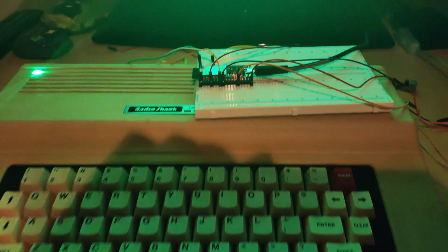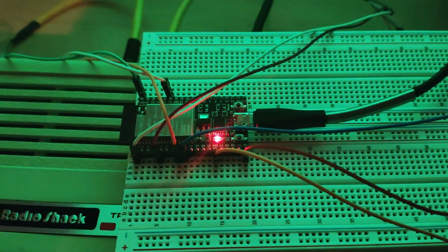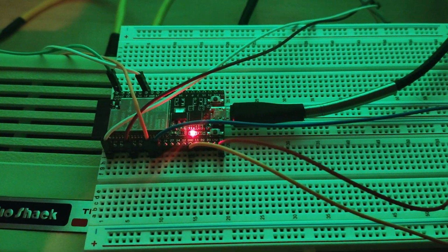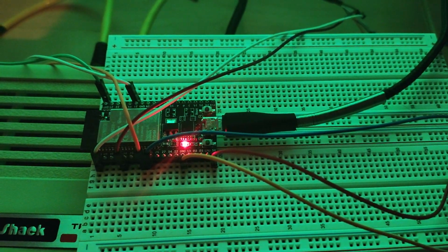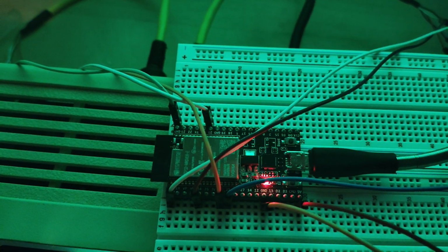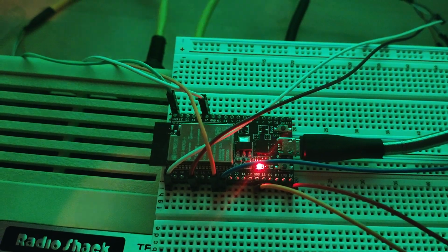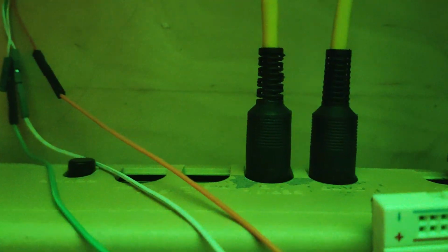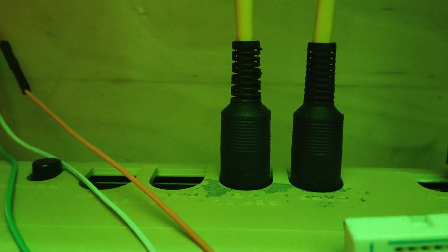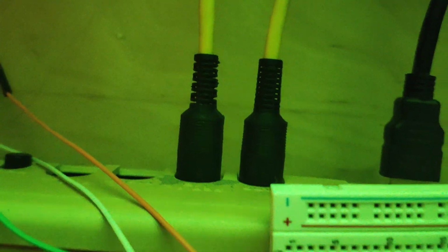Basically, we're in the middle of doing the bring up, which means bringing everything together and prototyping what we need on breadboards for now so we can get the software up and running. So tentatively what we have here is just an ESP32 module with a handful of connections from various GPIO, DAC, and serial ports going off to what are essentially the two connectors here at the back for cassette and serial port. The cassette is solely used for bootstrapping.